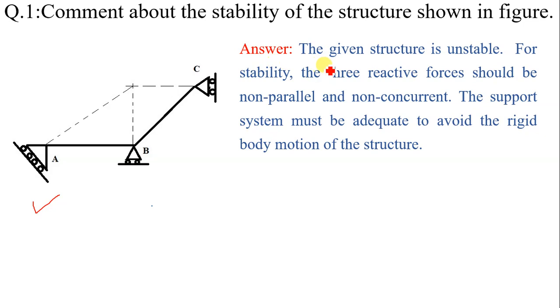The answer is the given structure is unstable. For stability, let us see what is the requirement. For stability, the three reactive forces should be non-parallel and they must be non-concurrent. Here the reactive forces are concurrent. They are meeting at this point, though they are non-parallel.